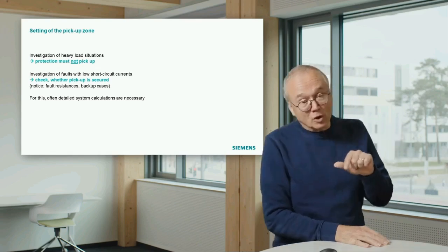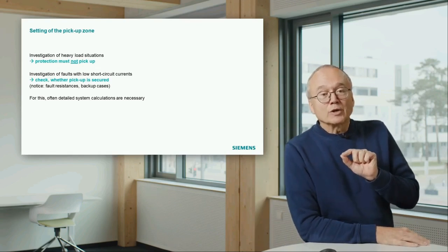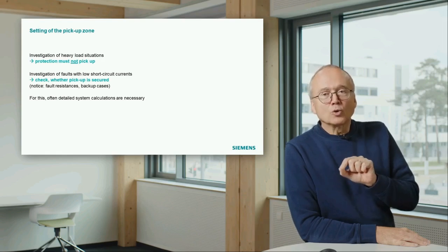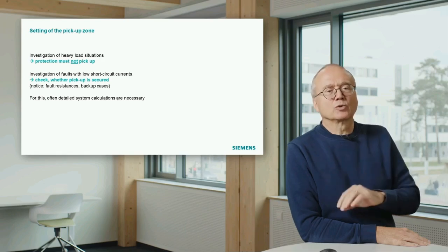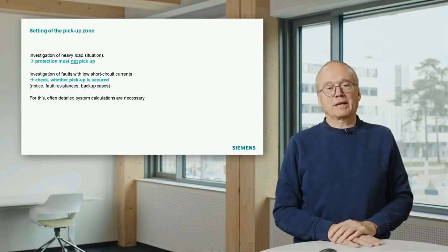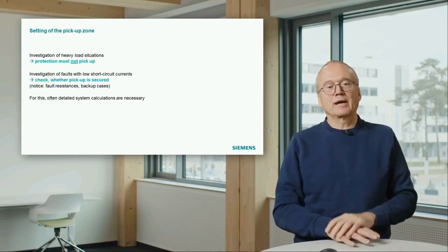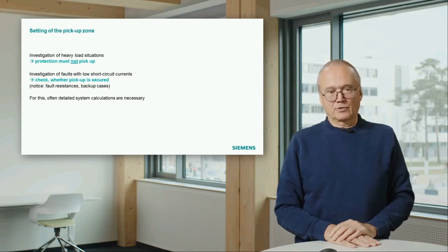And the other thing you also have to investigate is faults with low short circuit currents. That means you have to take into account fault resistances, and you also have to take into account backup cases. And also there, detailed calculations are necessary.